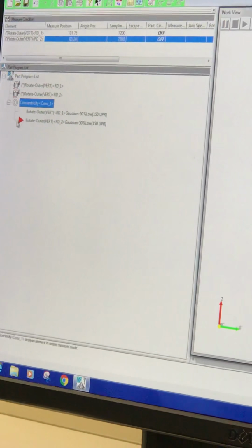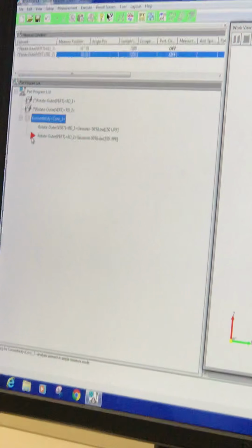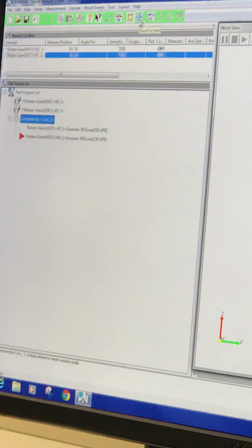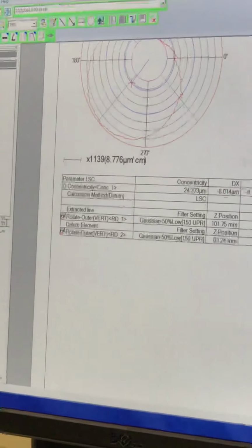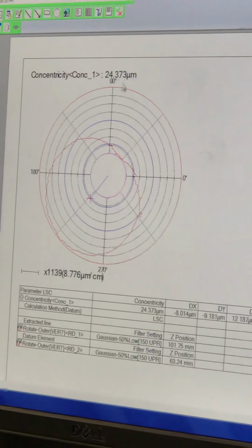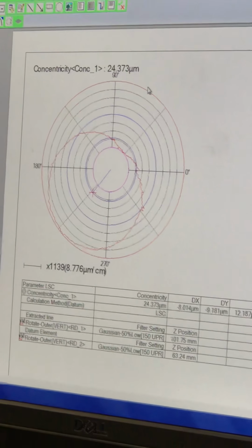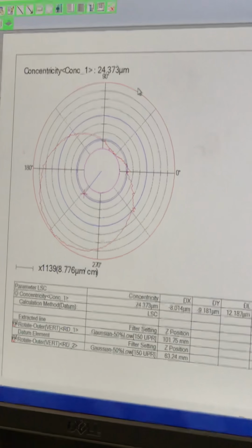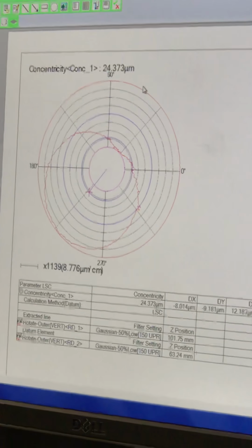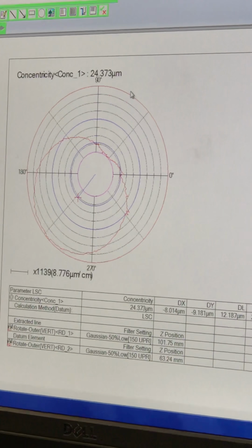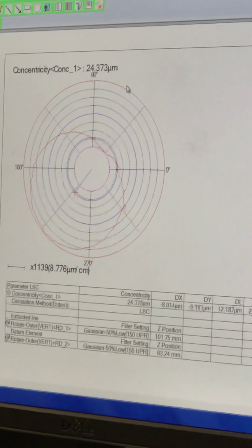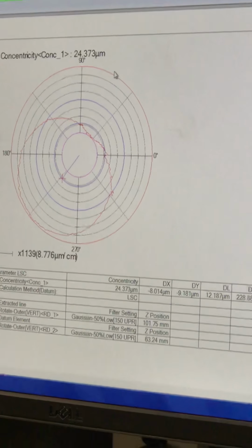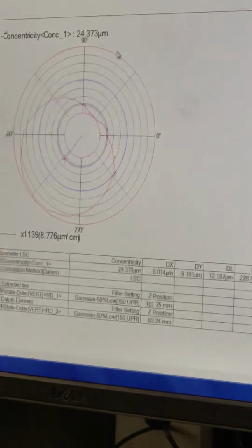Okay, then you can see there is red color here, datum. Then you can press the result screen here. Okay. Any question? Then record it down. So 24 micron, in or out? 20 out. Out by 4. Deviation is 4.3, 4.4. Okay, then you can go to PT.